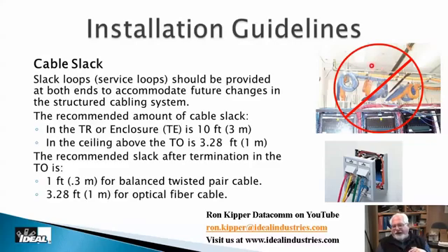Now, as you can see on this slide, you've got all these bundles up above in the ceiling. There's a bunch of coiled up bundles up there, right? That's a very common practice from years gone by, especially in an office building where you've got partitionable furniture underneath the ceiling, and that furniture is going to get moved occasionally. Having an extra 50 or 100 feet coiled up above in the ceiling, especially if you're nowhere near the 90-meter rule on that particular cable run, was nice to have, because you would not have to pull a new wire off the rack to move that particular office. So that was a very common practice.